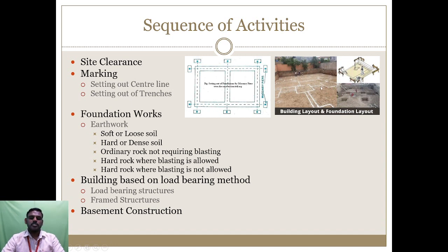If there are closed pillars, two closed pillars, it's possible to make a single foundation for the two columns. So the foundation excavation also we have to make in a single manner, but the size of the foundation will be higher compared to the previous one. If we are not doing like this, sliding is possible to happen in the space between the columns.